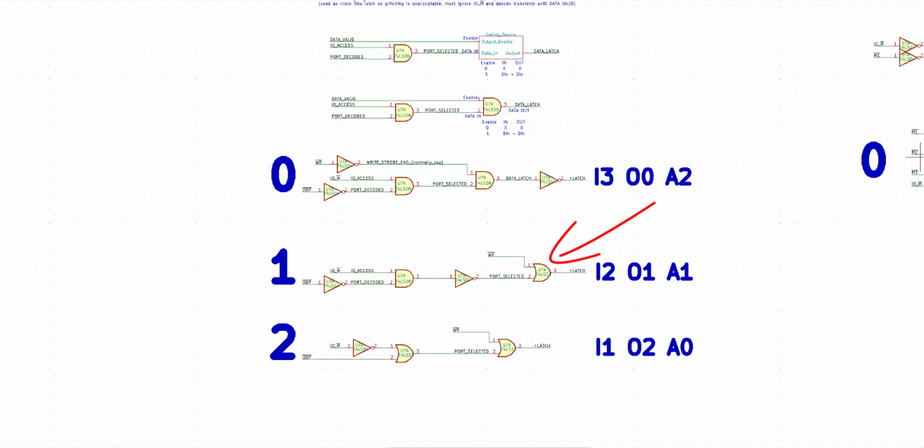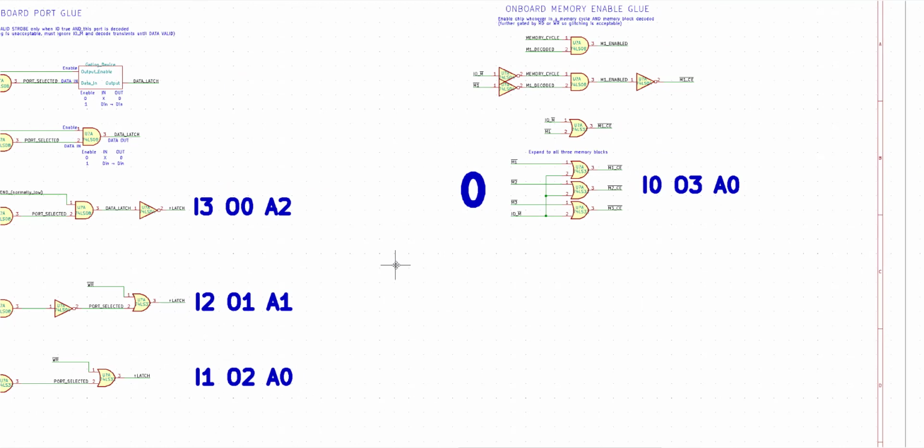Likewise, the OR gate serves as the gating device for negative assertion signals. So if you just keep that in mind, it helps having to refigure that out every time. Now on the last glue for the enables of the memory blocks, we didn't need to use a final read or write gating device since we aren't worried about glitches on its output, because internally those devices will use the read or write signals as their superior gating signal to get rid of any glitches.